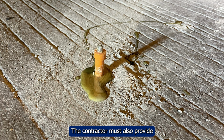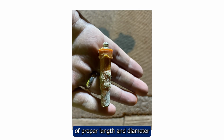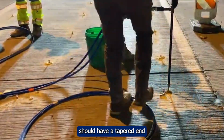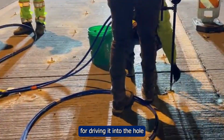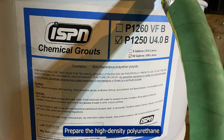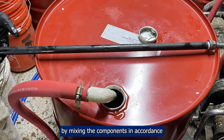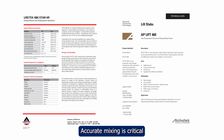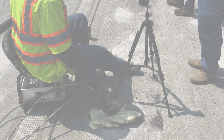The contractor must also provide cylindrical plugs of proper length and diameter to seal the holes. Each plug should have a tapered end to allow for driving it into the hole up to 2 inches deep. Prepare the high-density polyurethane by mixing the components in accordance with the manufacturer's specifications. Accurate mixing is critical to ensure proper expansion, bonding, and long-term performance.